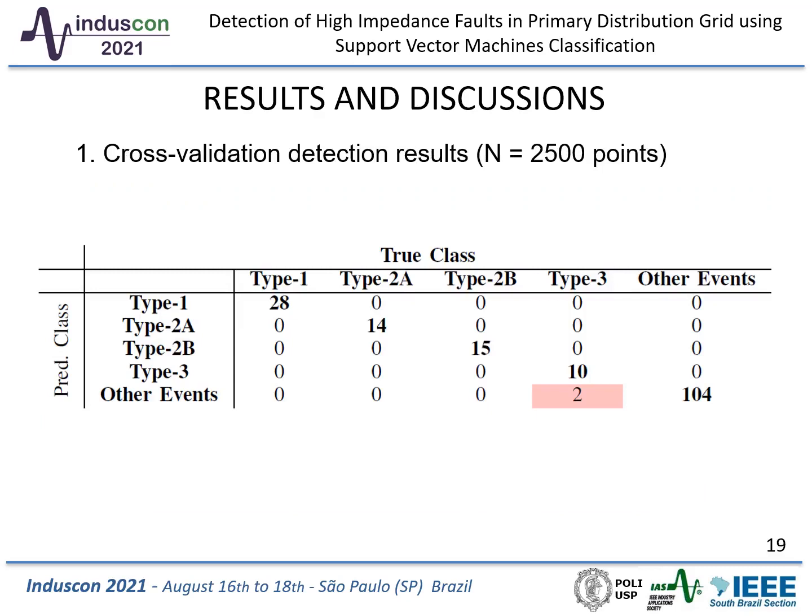To verify the reliability of the detection stage, a cross-validation system was created. The occurrence of each transient phenomenon happened individually, based on 20 random simulations that lasted 5 seconds, totaling 173 different events. That is, the insertion of a new transient phenomenon occurs instantly after the removal of the previous one. Each of the events occurred at a random position L along the 45 km feeder. Besides, the choice of the phase A, B, or C, where each event took place, was also randomized.